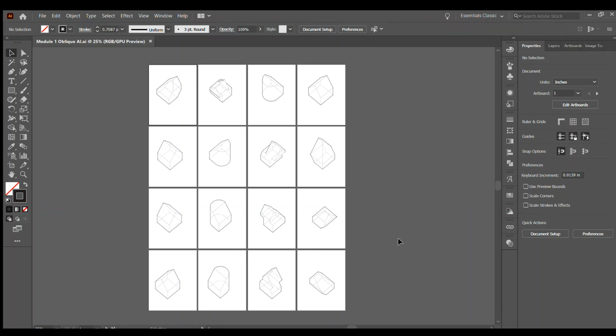So I've placed my DXF file in Illustrator, and then like last time, remember to make sure that all your lines are completely black, and then change your line types if necessary, but otherwise if you did that in Rhino, and then place your DXF file, edit your lines, and then take out the artboards if needed, edit your artboards, and then organize your file, and then you are good to print.